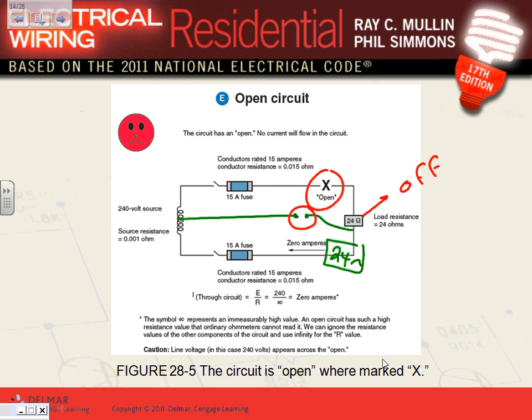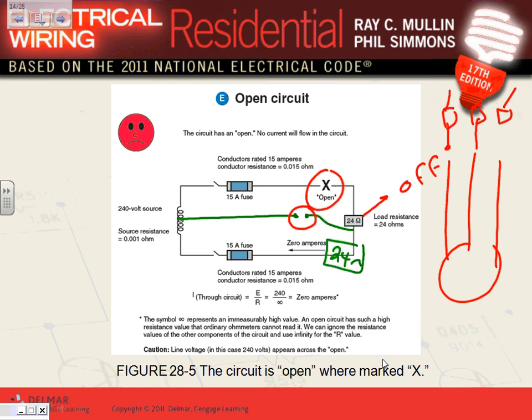Take this. If you have a three-phase motor, 1, 2, 3, and you have your circuit fuse here protecting a three-phase. We'll talk about this one, guys. And everything is tied. And oops, I have a fuse open here. So actually, what happened here? I have a fuse open. This is a 50 horsepower motor, three-phase, 480. Is this an open circuit? I have a phase open. That's an open circuit. But I have two more phases still up and running though.